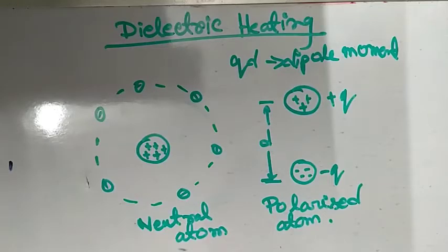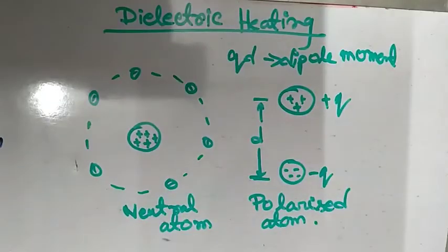It is observed that the loss increases with increase in frequency and strength of the electric field. However, if the electric field applied is very strong, it may overstress the charges and hence some electrons may be knocked off from the outermost orbit and resulting in rupture of the dielectric medium.